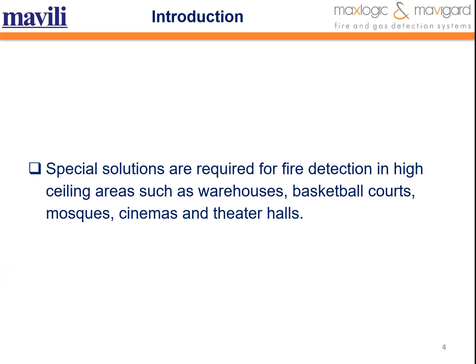Let's start. Special solutions are required for fire detection in places with high ceilings such as warehouses, basketball courts, mosques, cinemas, and theaters. Optical smoke detectors, which are frequently used in spaces, go into alarm when the particle density in the photoelectric cell reaches a certain level after the smoke caused by the fire reaches them. So in places with high ceilings, it will take time for the smoke to rise to a certain height, so it will be late for the optical smoke detectors to detect fire.